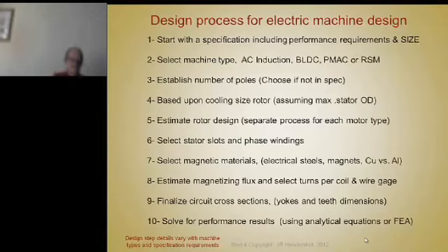And a common one is a half a slot per pole per phase, which would be like a 6-slot stator, 4 poles. So 6 slots divided by 3 phases is 2 slots per phase. So divide by 4 poles, and you get a half a slot per pole per phase. So that's a fractional slot winding, but that's a winding whereas the coil is wrapped around a single tooth,